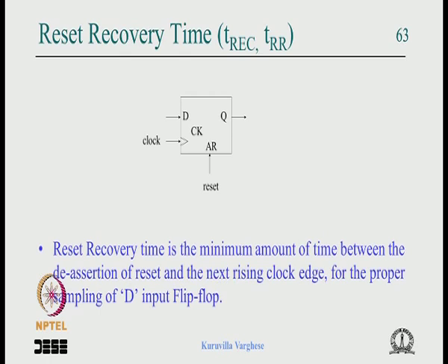Again in this course I do not have time to go into the details because it will eat up our time. So they are driving the master and slave latch directly, not going through this clock gating, that is why it is asynchronous. As soon as you assert it, with a delay the output is reset, the clock does not matter because it is going directly into the latch, and what the clock does is gate the input to the master latch and so on.